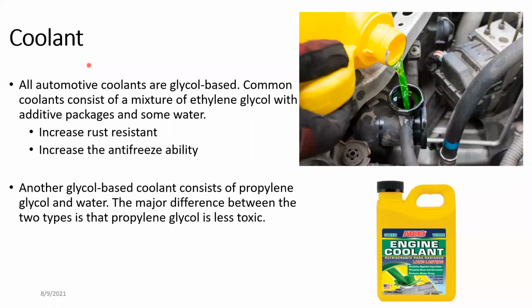So because of that, coolant needed to have rust resistance. Plain water tends to rust the metal, and it tends to freeze and become dense, right? To avoid this, coolant is being used. Coolant increases the rust resistance and increases the antifreeze ability, so it will not freeze if you use coolant.